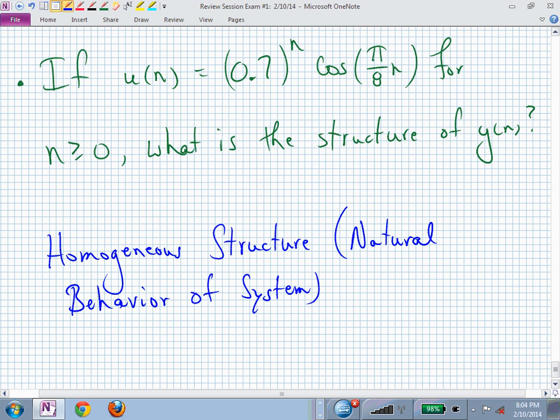You basically have initialized the initial conditions, and it just now shakes. And since it's stable, it's going to be a well-behaved response. That would be the pulse response in a discrete system. It's the impulse response for a continuous time system. You hit it with an impulse, that just energizes all of your energy storage elements, and then you just watch them decay. That's what we're doing here, except in discrete time.